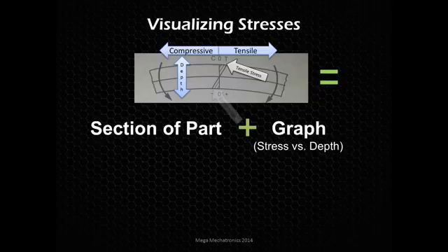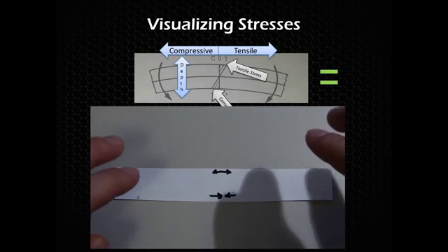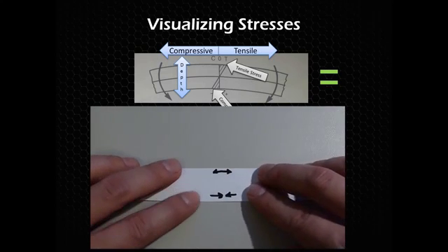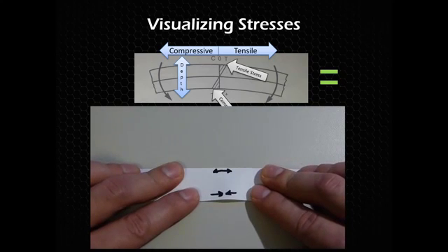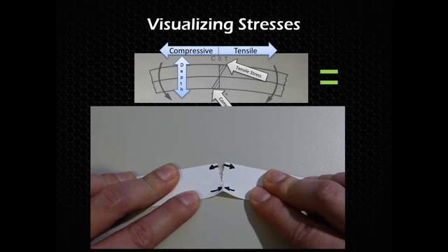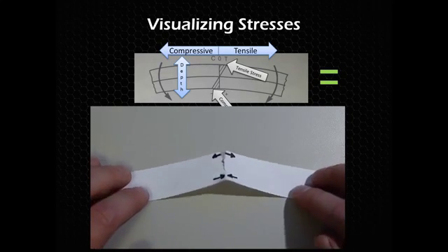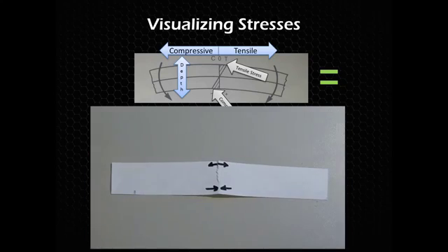And that's typically how parts react to stresses, where the surfaces are seeing the max stress. And in our video example, you can again see how I'm bending that piece of paper, and it's going to pull apart at the top because it's under tensile, and then you see it buckling at the bottom because that paper is trying to come together, but it'll buckle up.